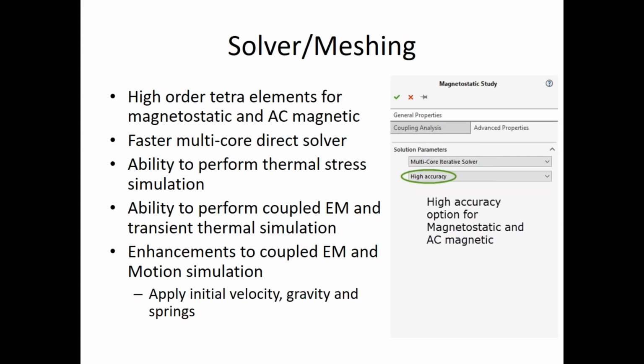For example, when you do a steady state thermal simulation, it tells you everything about the final temperature distribution, but you have no idea how long it takes to reach that temperature. Now with the transient thermal simulation, you will be able to get a sense of time and how hot your bodies get at various intervals of time.